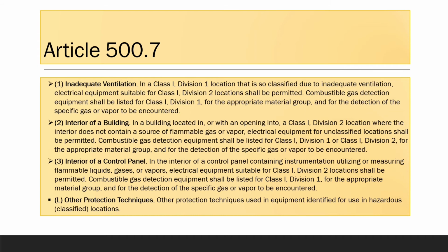Inadequate ventilation can lead to the buildup of small amounts of contaminants which are difficult to identify and test. So carbon dioxide levels are used as an indicator of adequate ventilation in a room. Carbon dioxide is released by combustion of fuels and every time we breathe. It is normally measured at 300 to 350 parts per million in the atmosphere.